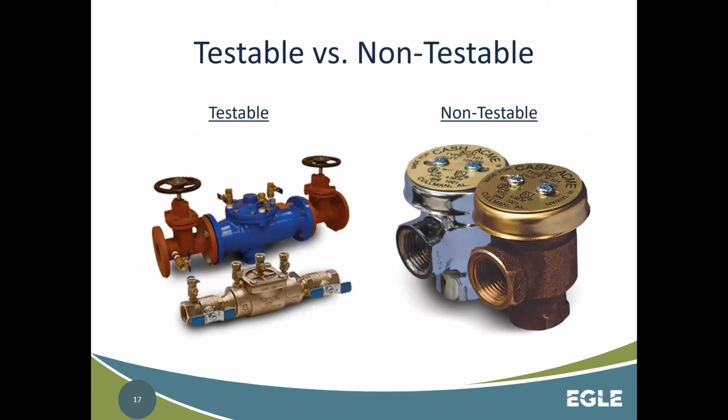Here's testable. So testable, you see these test ports here. What these are located in the areas between the different valves within this that allow the tester to isolate them and be able to check the pressures to make sure they're in proper working order.